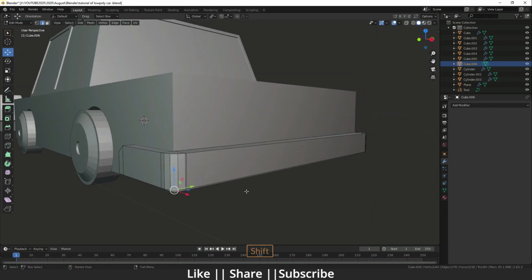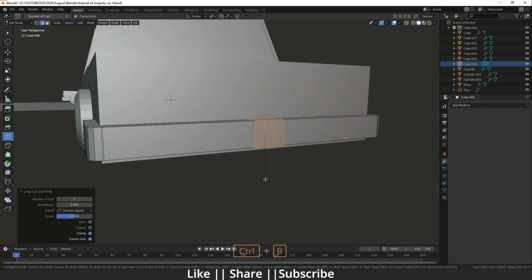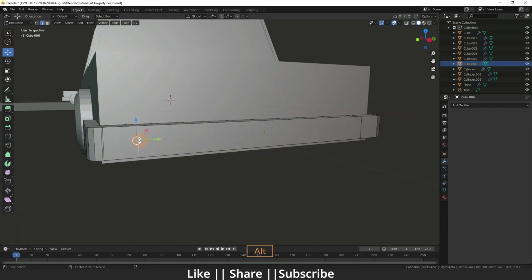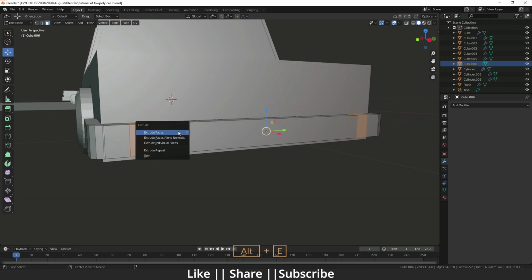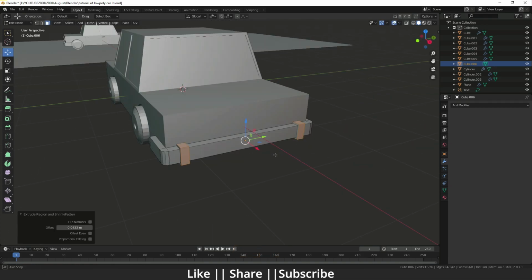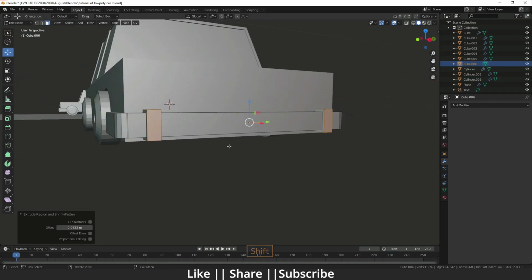Okay guys, so now I'm just going to add one edge loop here, and after that I'm just going to select both edges and do bevel like that, and go to the face mode, and I'm just going to press Alt E for individual face extrude like that. So we have an individual face extrusion like that.